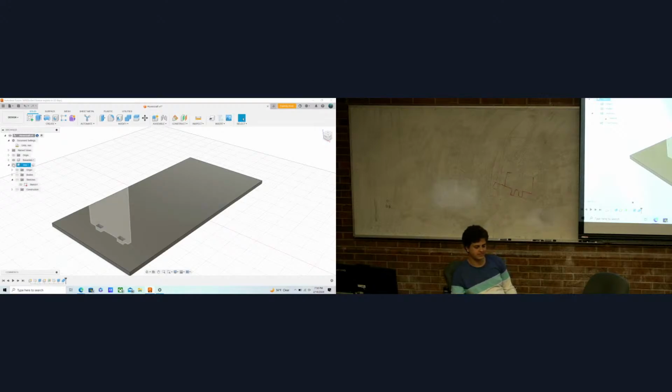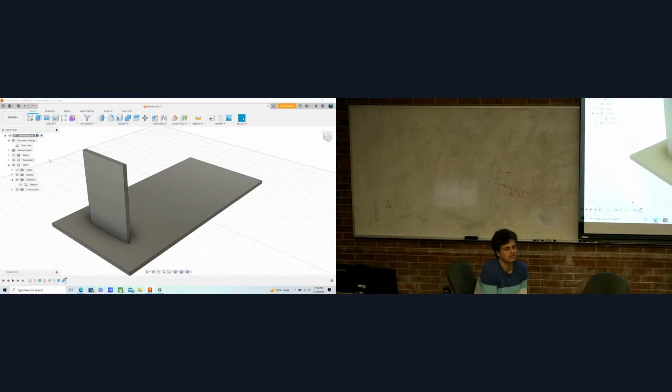So we're going to modify it, okay? And it should be the combine tool in the drop down here, and it will do it automatically because you had it. Everybody else able to get here? For the tool body, select the filter project, and select where we want to have it. And then we want to change the operation to cut, because right now it's in combine.